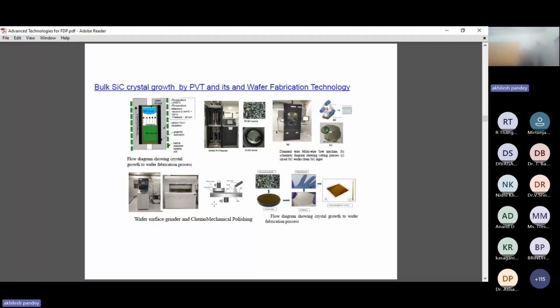But one more thing which I have not included here before that: because the as-grown wafer is a 4-degree cut, orientation will also be done. For orienting, there is an X-ray goniometer. Using that, it has to be oriented along the 001 direction, and there is a flat demarcation also, like a primary flat or secondary flat, and a primary flat grinding machine is also there to make the primary flat, secondary flat grinding, then cylindrical grinding, these several steps